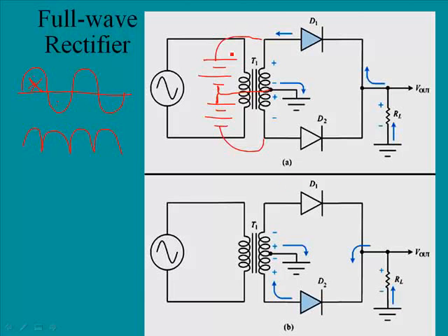What we actually have is our input waveform coming in, positive to negative, and sometimes it's helpful to view this. Remember that on this one, actually this waveform is reversed, and so instead of going positive first, notice it is negative, and so on this side we could view the signal as going like this, because here it's positive and here it is negative. So the idea of this type of device is that one diode will be on and the other will be off.